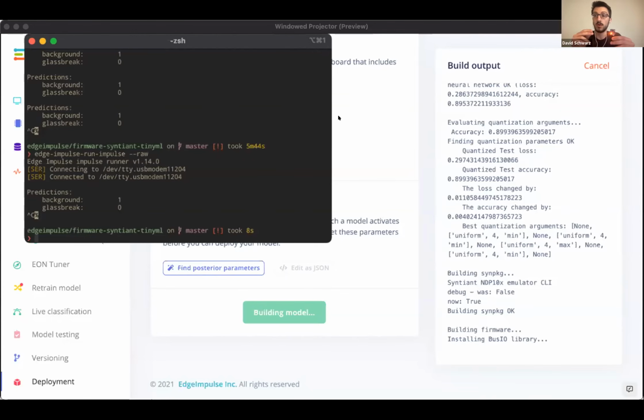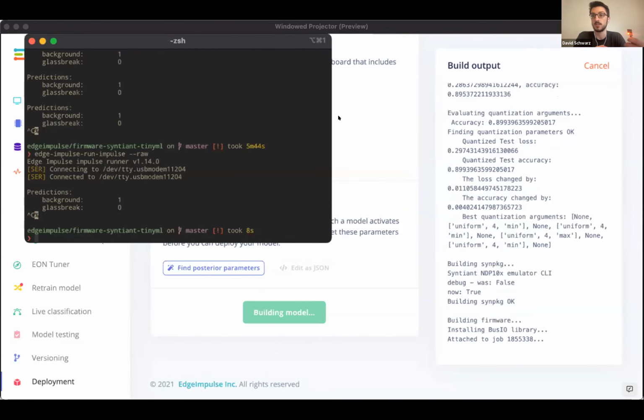And it's going to utilize the really low current consumption that the NDP offers to continuously sample the environment and determine if interesting events are occurring. If an interesting event, specifically here, a glass break event occurs, it's going to turn on an LED. Simultaneously, it's going to output the results of the inferencing, that continuous listening, to the terminal, which we can view here.